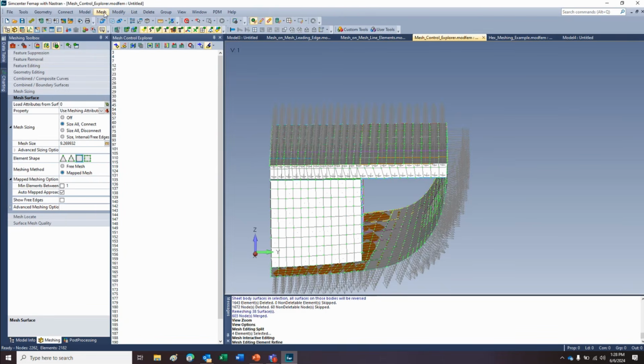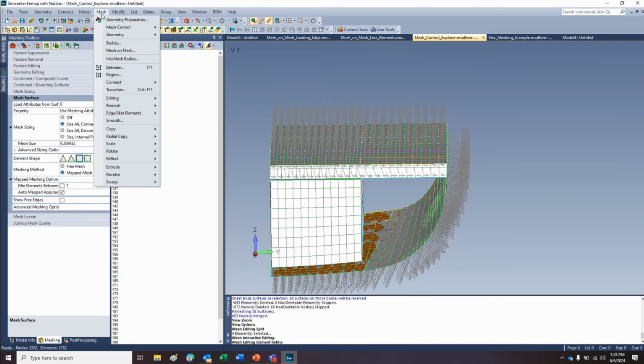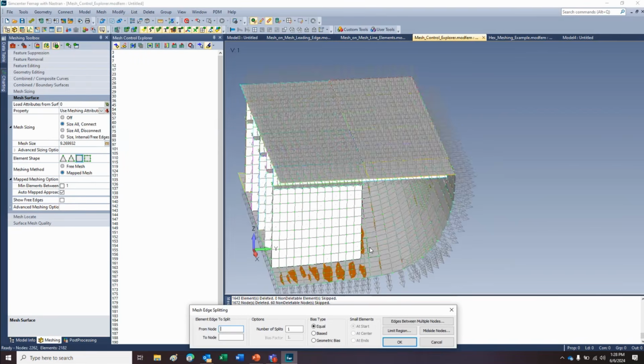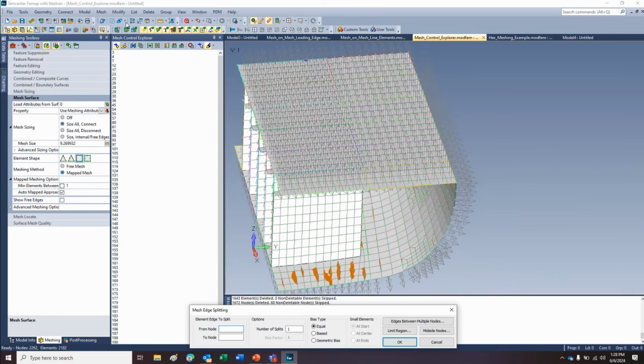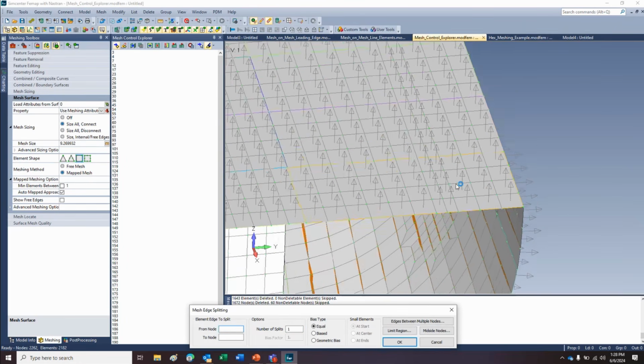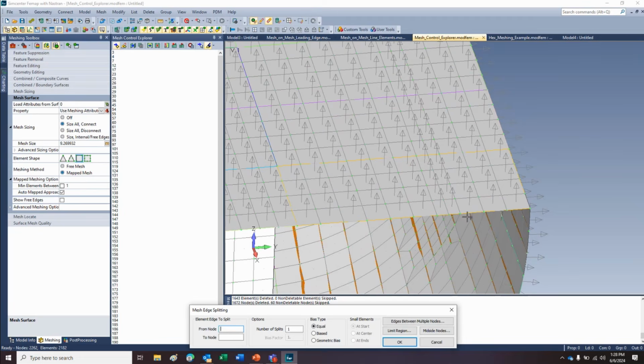So, one of the other things that was in here, I know it's not going to work because they're not. Oh no, they're connected. What am I saying? So if I go to editing and I use the edge split, hopefully everybody knows about this one. This one's really cool. This has been in here quite some time, but you can even come around a corner like this. Here, I'll just do it once. And it just splits them all the way down the line. And again, it's purely doing that based on proximity because it's just going connected element to connected element.